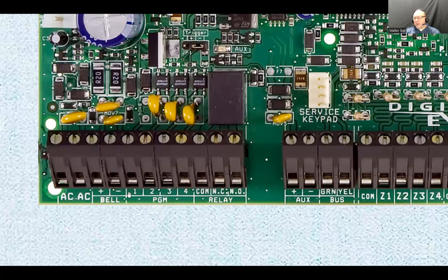Now, if these program terminals are designed in a way that when one of them is activated, there is a 12 volt DC voltage on it, then in combination with the dry relay contact, you could control all kinds of other devices, maybe some third-party devices like door strikes, or some other things that need to be powered up or need a dry contact relay. So you have a bit of flexibility, and how exactly this works varies from manufacturer to manufacturer.